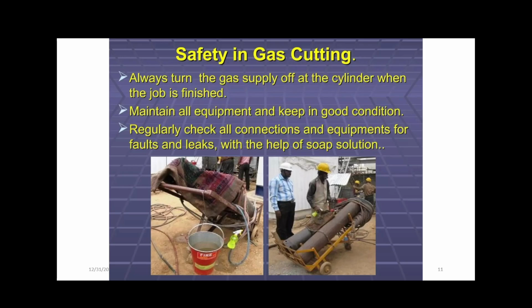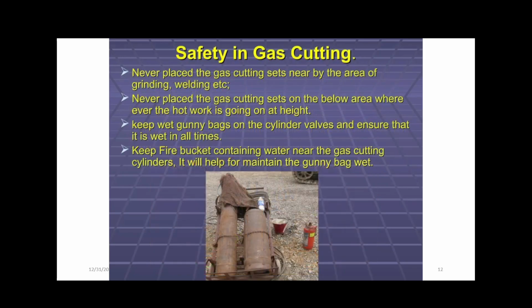Always turn the gas supply off at the cylinder when the job is finished. Maintain all equipment and keep it in good condition. Regularly check all connections and equipment for faults and leaks with the help of soap solution.